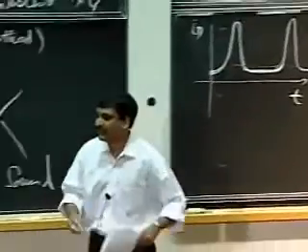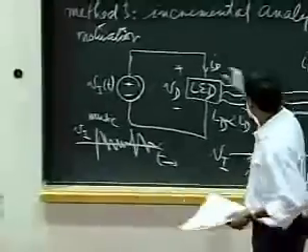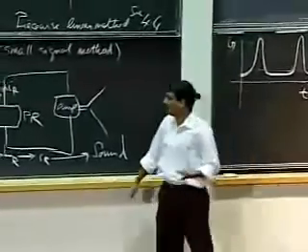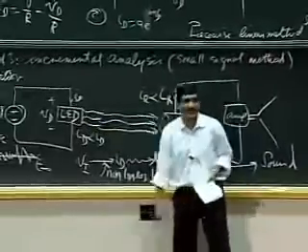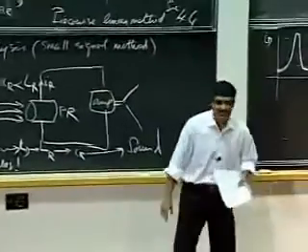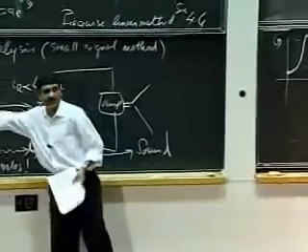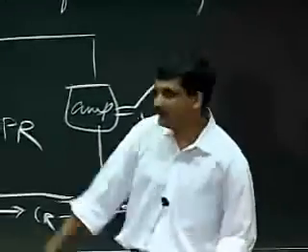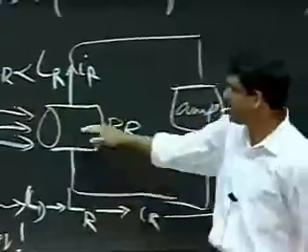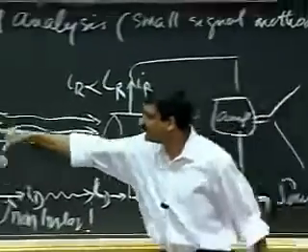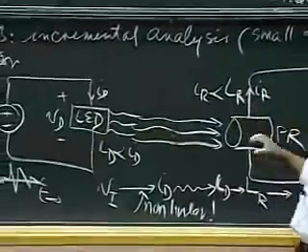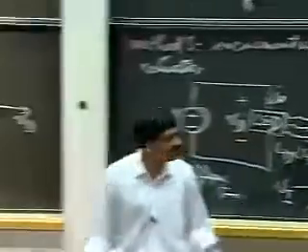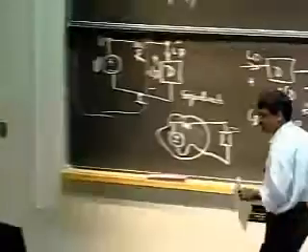So I'd like to show you a little demo. We've gone ahead and built a little device like this. We have an honest-to-goodness little device, costing I don't know, 50 cents or $1 or something. It's a device that emits light proportional to the current flowing through it. I have a receiver, and I'm going to play some music, and you will listen to the output here. Hopefully you should see a bunch of distortion because of that effect that I showed you.